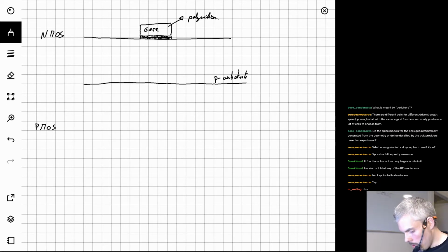So that creates one of the terminals of your NMOS. We tend to forget it, right? But the NMOS is actually a 4-terminal device. You have the gate, the source, the drain, and then you have the bulk connection. If you buy an NMOS in a SOT23 package, you'll usually have the bulk connection connected to the source, and so you only get 3 terminals.